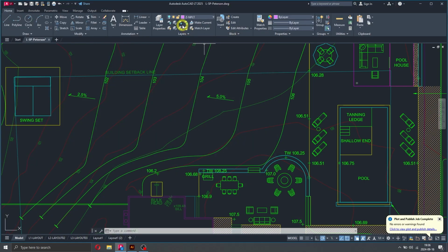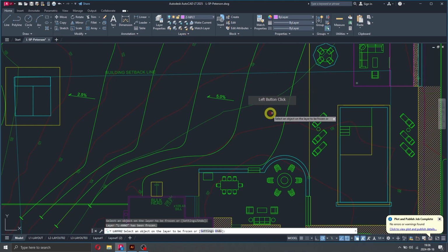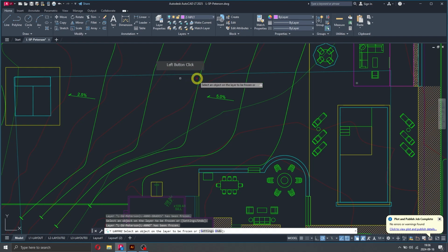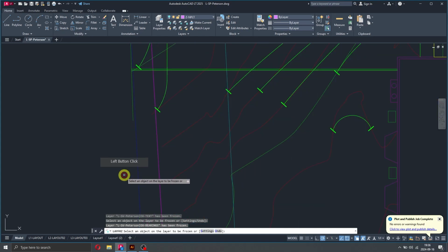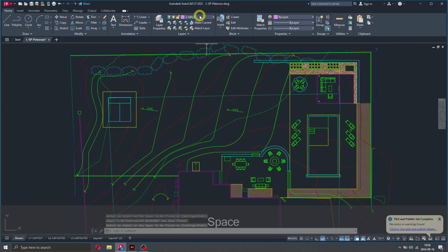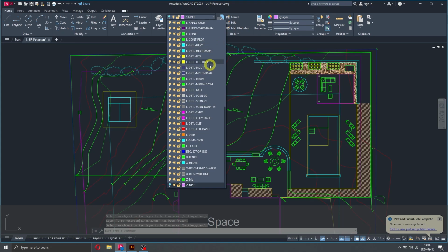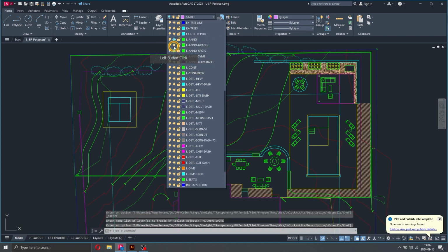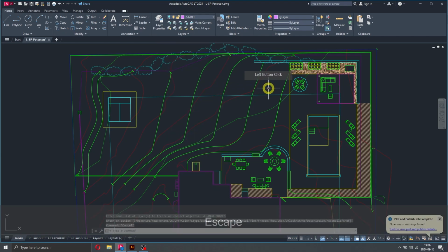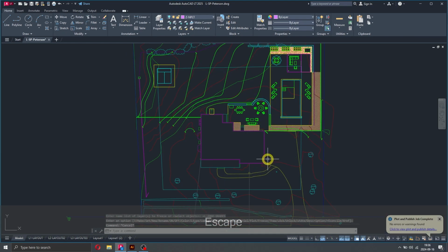And then I'm going to go through and turn off or freeze all these text items. Some of these are XREF, so I need to do it this way. I think most of that's gone. That's fine. These are on symbol, so I need to turn that off. Also use a layer called AnnoSim. There we go. Let's turn all this off. That's fine. So now I pretty much have a drawing, no text.